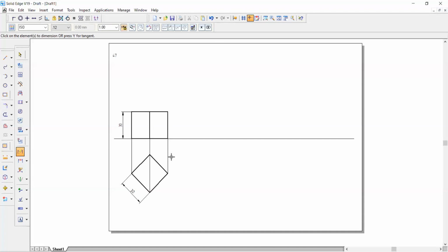After this particular condition, he says such that one of its solid diagonals is perpendicular to VP. Solid diagonal perpendicular to VP is your final answer. We know that generally in a prism, whenever he says the axis is inclined, we are talking about beta.